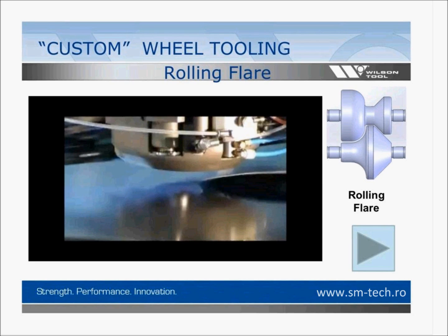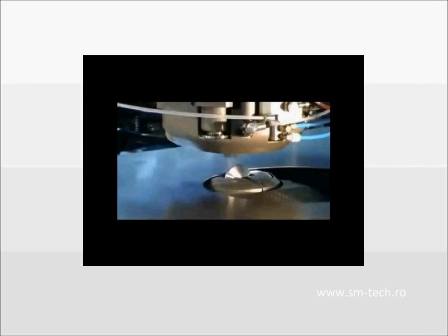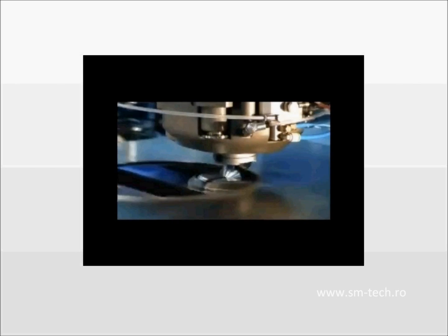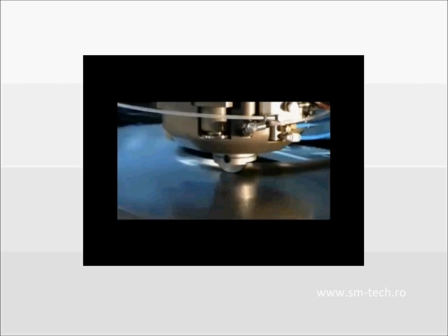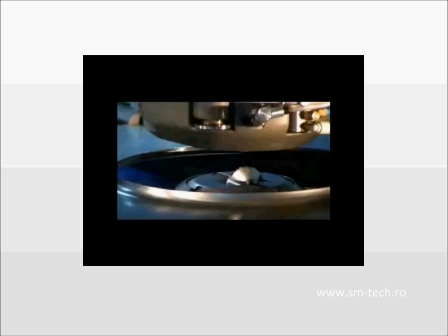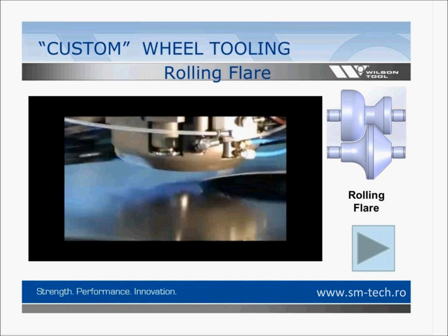This is a tool we call a rolling flare. Now let's show a quick video of what that looks like when it runs. It's very often used around the inside of a hole, maybe for a blower housing or something like that. It forms up that edge and comes up to close to 90 degrees. How high we can go with that depends on a lot of different factors. One of those factors is the feed clearance of your machine, but also the material type and thickness is very much a matter of determining how high we can go with this rolling flare concept.